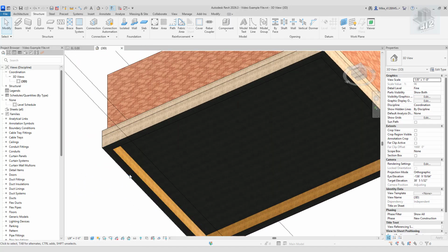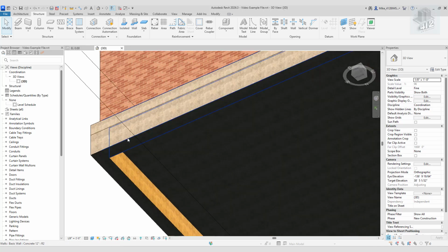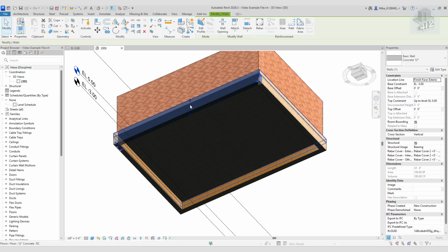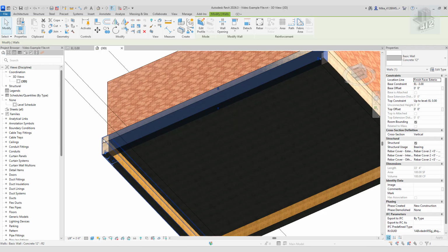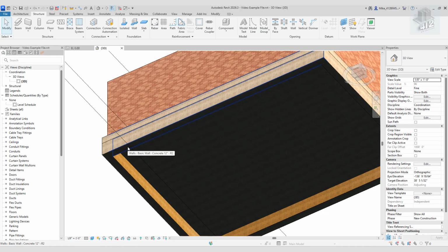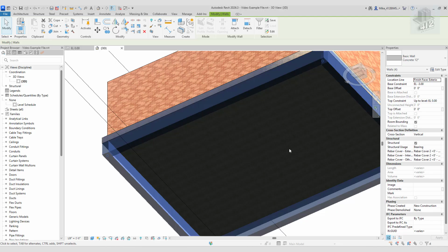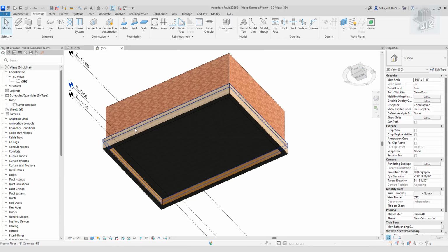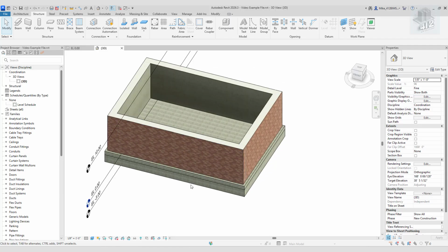the wall in place. Now one thing I do recommend is cutting the tops, putting the offsets back on the top to be negative whatever the floor is. So if that's a 12-inch thick floor, what I'll do is I'll hit tab and select. I'll go up to here and I'll say -1 foot, and that will pull it down. At some point you're going to need to join the materials, but that's a topic for another day.